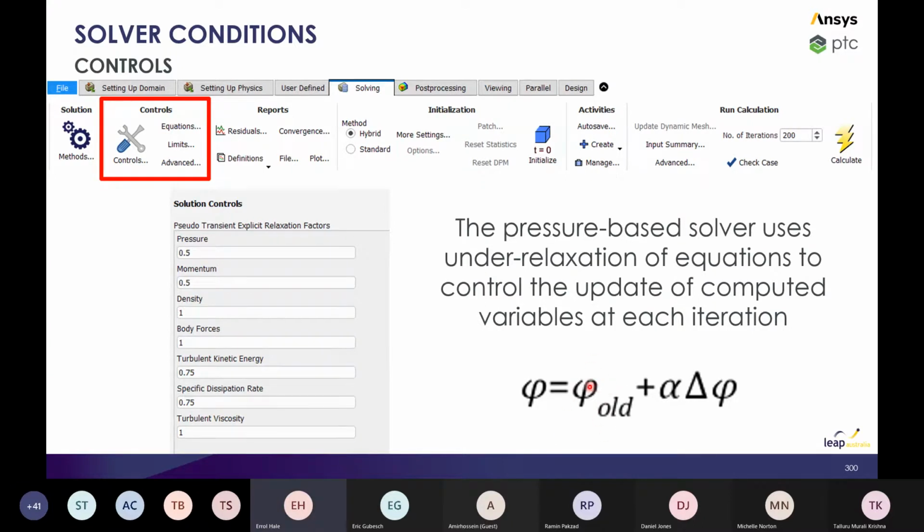so at iteration, say 1, we've got this value for pressure, density, velocity. We then run our iteration and we get our iteration 2, we get another value for that pressure. Let's just call it pressure. So we've got pressure 1 and pressure 2. When we use under relaxation, we don't take pressure 2 and then plug that into our next iteration. We take some fraction of P2. And the reason for that is because it allows us to converge more slowly to a solution.